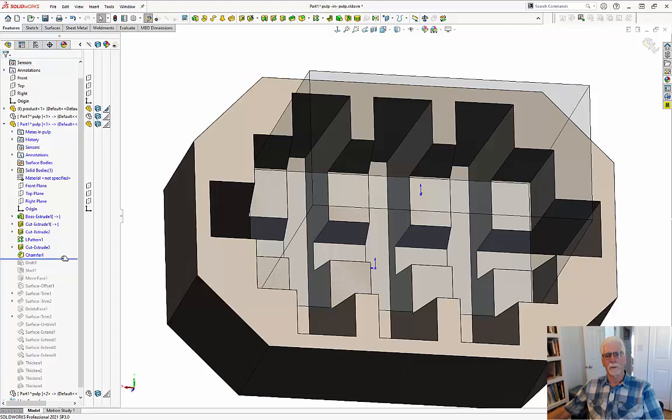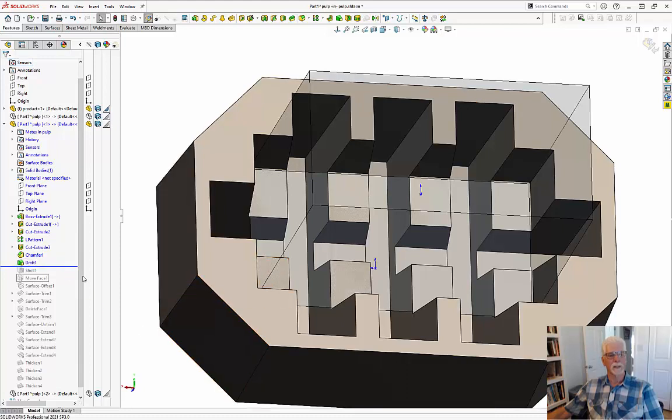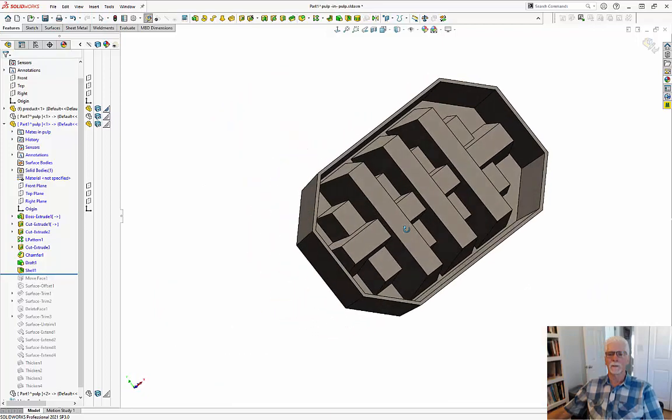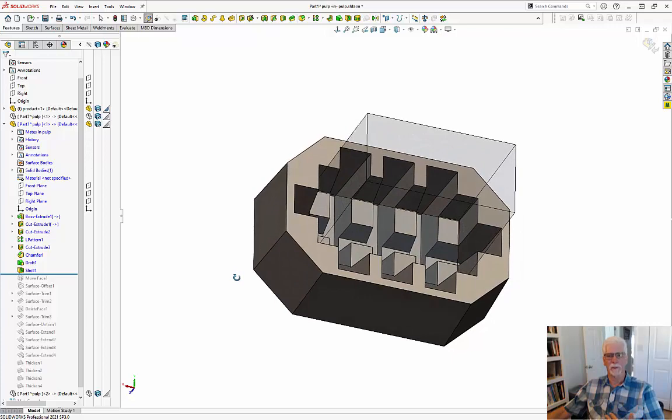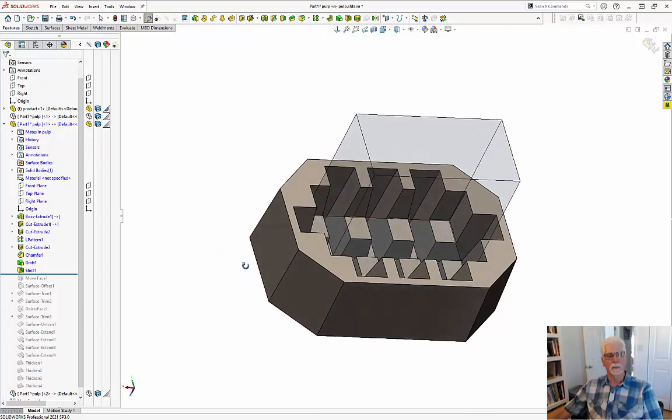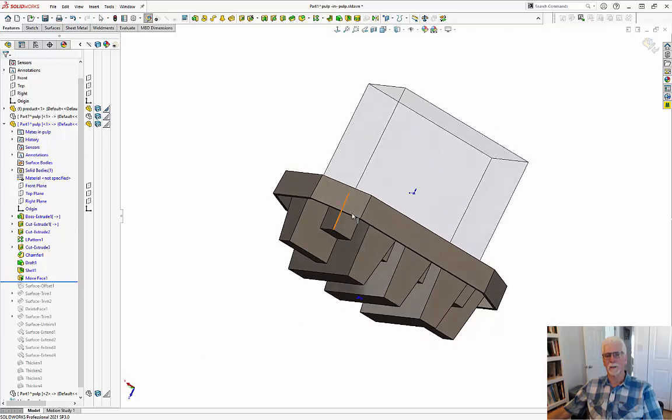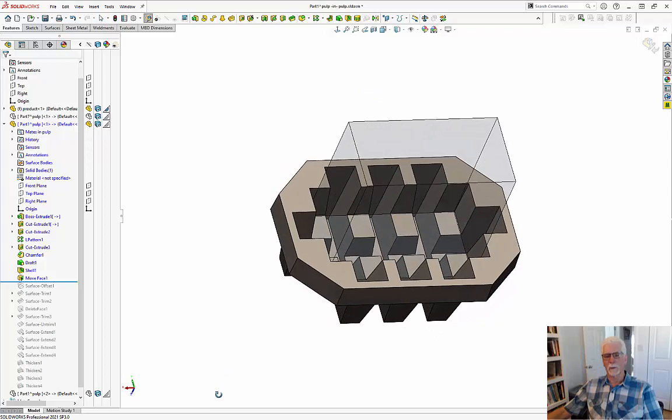And then we put chamfers on the corners, because on pulp the corners like to warp. And then I put draft on the outside, and then I shelled it from the back side. Okay. And of course, if you were adding fillets, you'd put the fillets on before you shelled it. And then I move the face on the bottom so we get what we call a skirt. And then that's our finished part.